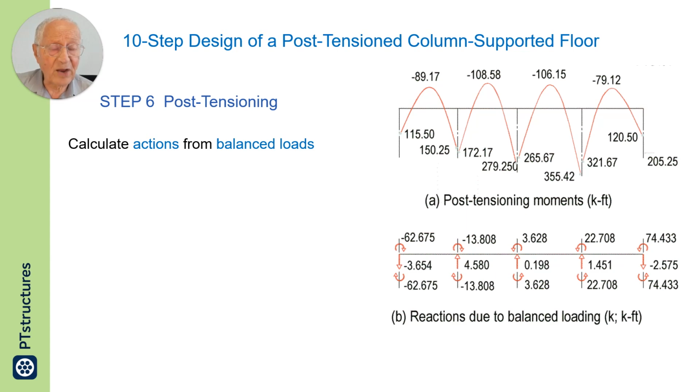program in the way that we applied the dead load and the live load. Now we apply the balance load to our frame program. Application of balance load to the frame program gives us the bending moment diagram on the top due to post-tensioning, and the reactions.